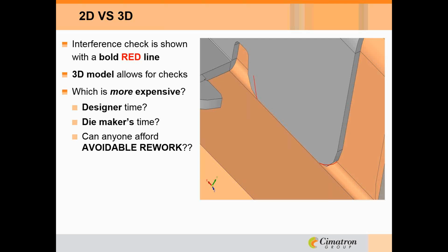Now what happens if down the road you need to replace that V-block, you go back to the print, you're in a hurry, so your shop foreman says, oh, let's just kick that on the side and put it in our wire EDM and burn it out. Well, the corner is still going to have that radius, and it's going to do the same thing again. All right, so having the system integrated where the prints know what's happening to the parts and where you can see the changes and keep those changes is definitely going to save time.